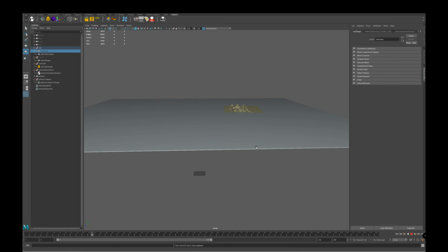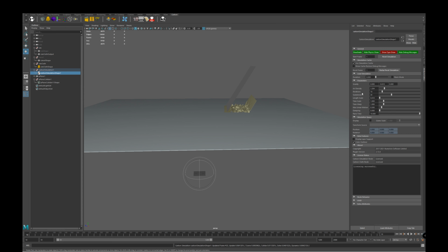That looks good. As I'm going to run a slow motion render, I want to record the simulation with a lot of frames per second. So I'm going to change the FPS now to 240. Because we have a lot more FPS, now we can wind back the simulation settings because they are per frame. So 5 iterations per subdivision and 20 subdivisions per frame is going to be more than enough. Let's just check that that runs okay.